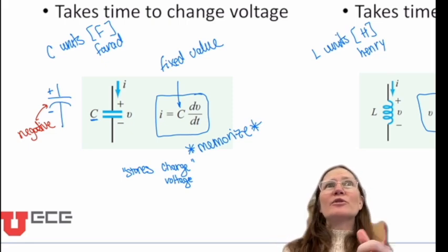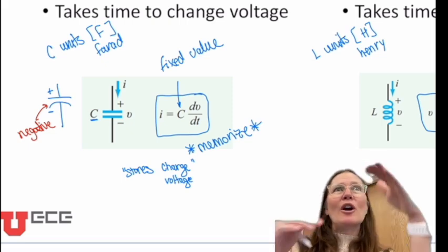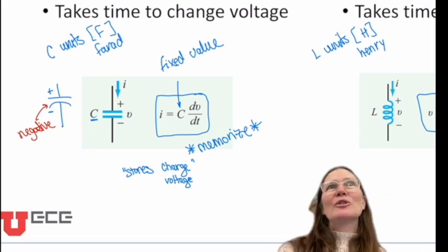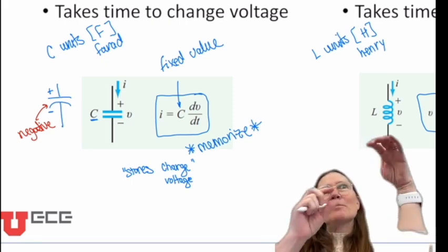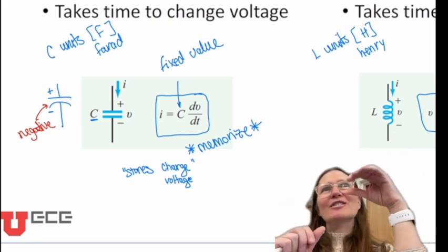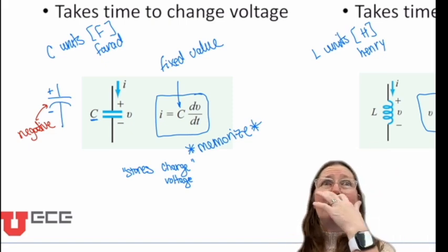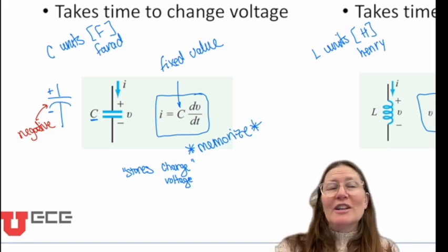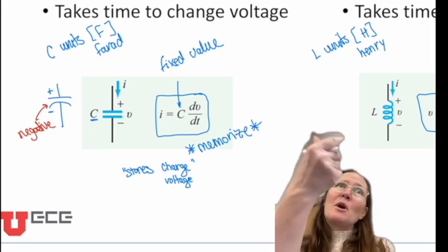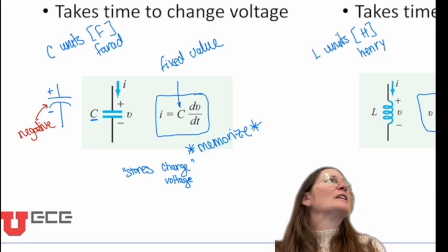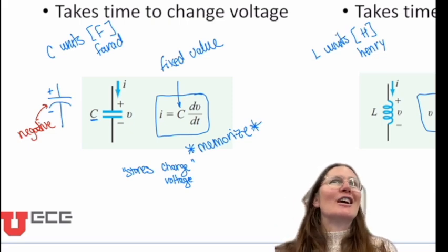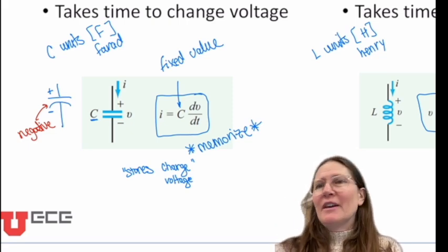So they use different materials. They are actually different materials on them. Some of them have a dielectric difference and some use different metals on each side. That's why there is a charge difference on them: the materials are different. If they were the same, which is what most of them are, then it's interchangeable. But in the polarized ones, there is an actual difference in material.